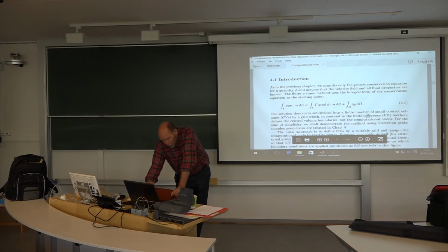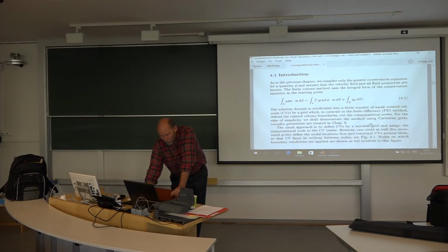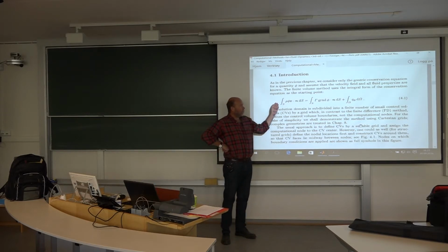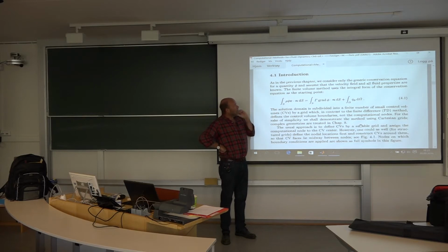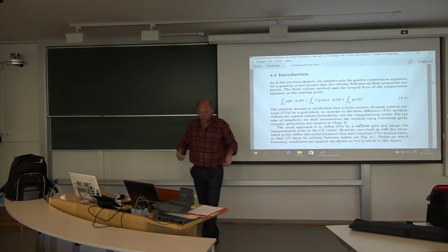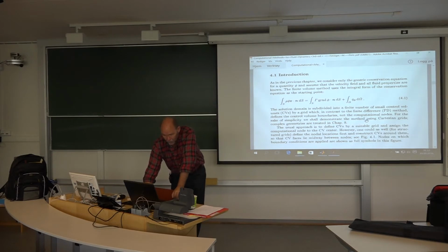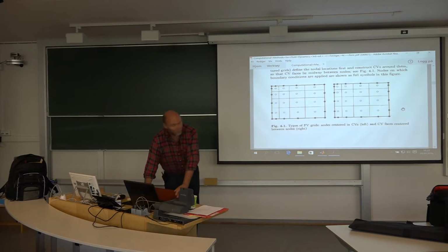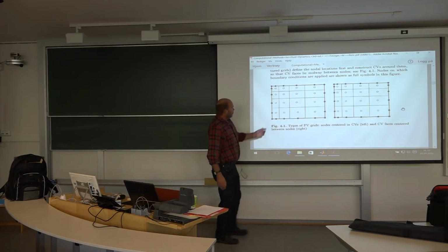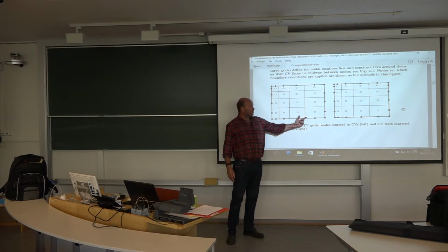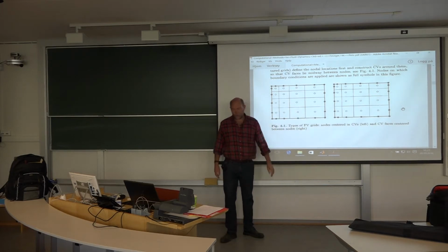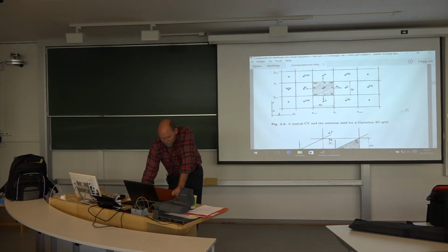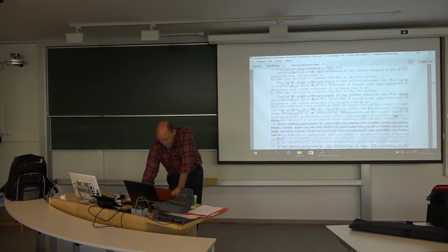But for now, just trust me when I say the algebraic equations we end up with using finite volume will be identical to the finite difference as long as we are using a rectangular mesh, delta x equals delta y, then everything should be a-okay. Here, of course, you see delta x not constant, it changes. So that's not for us yet. So we just use a rectangular mesh.